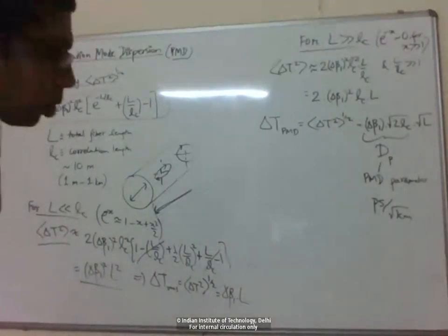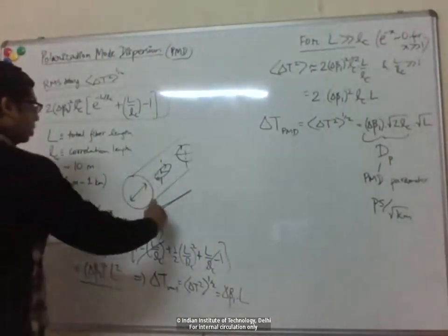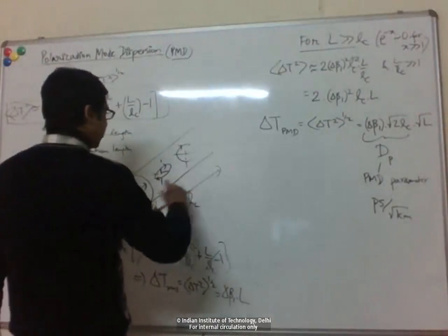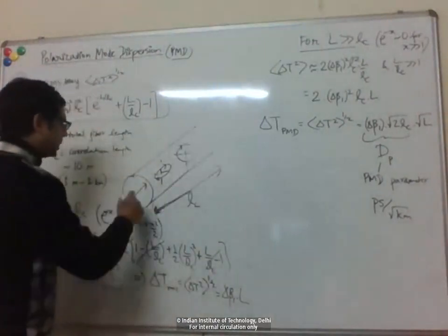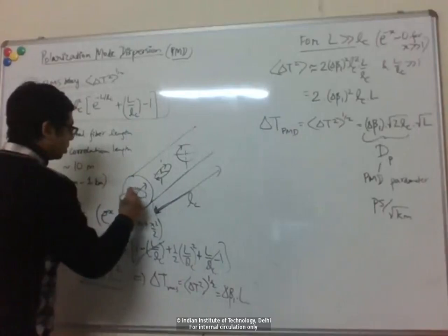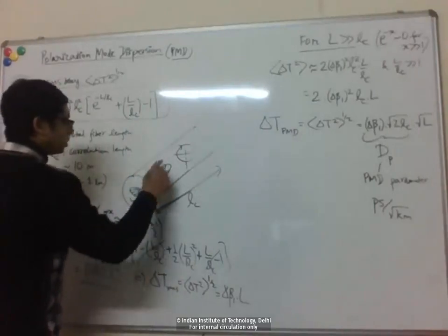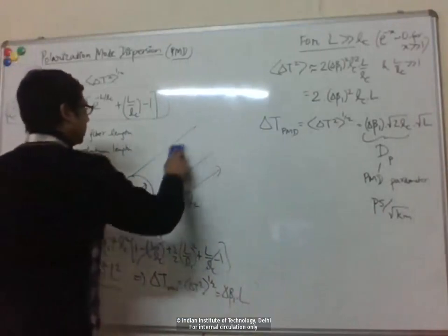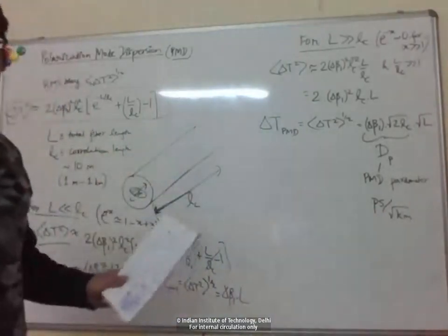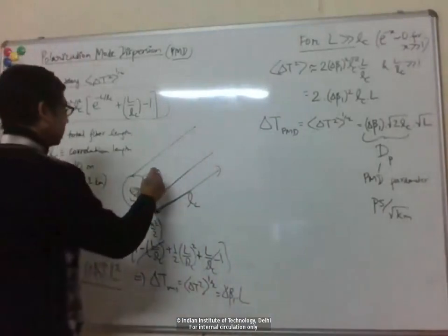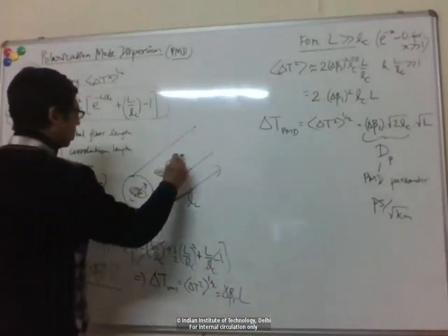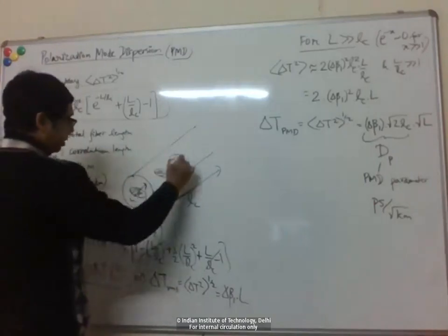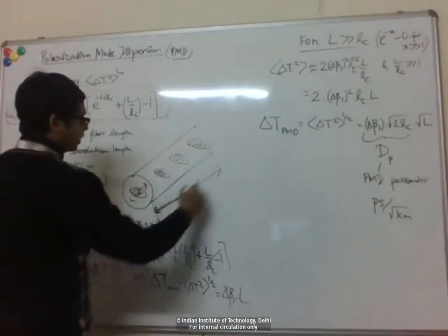So somebody has asked about correlation length, right? So it's the length over which the birefringence is constant, right? So basically the core looks the same over this length, right? Or equality, like the stresses on the fiber are the same over this length, right? So if you look at the core, maybe it's compressed in this direction and elongated in this direction, but it's the same over this correlation length.